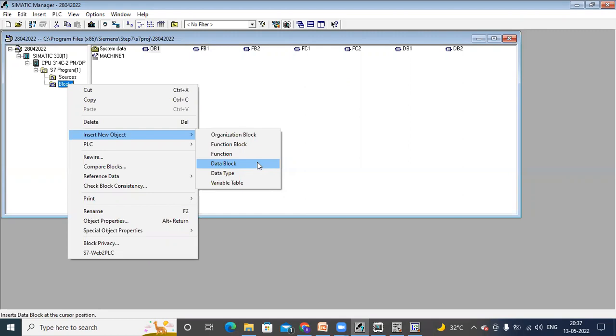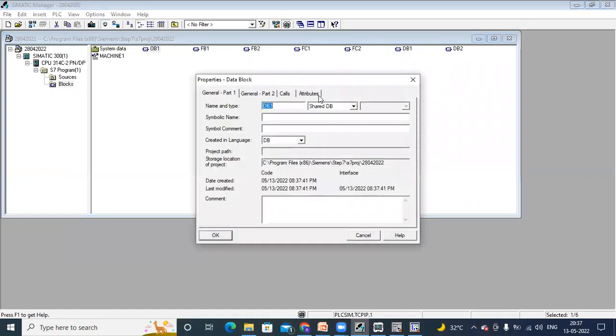Here we need one structure for some machine, for some process. We have some analog values and digital values also, right? For storing their status, I need some memory. So for that I can create one structure here in the data block. I can create one structure, meaning for this temperature I need this memory, for this pressure I need this memory. So I need not keep calculating how many bytes and which byte number we have to use. Here you can directly create a list in the data block.